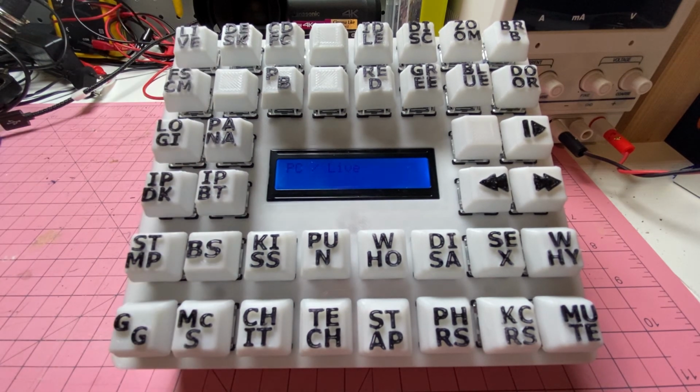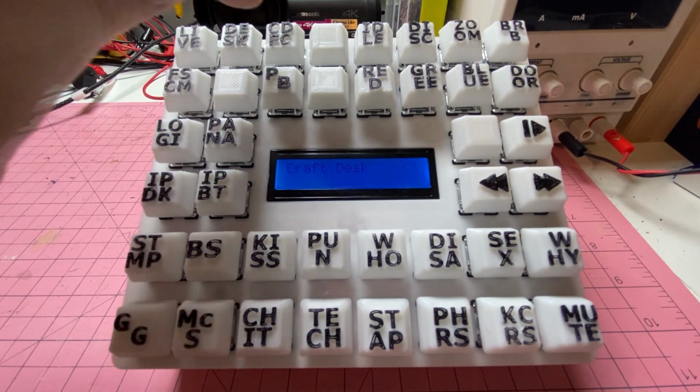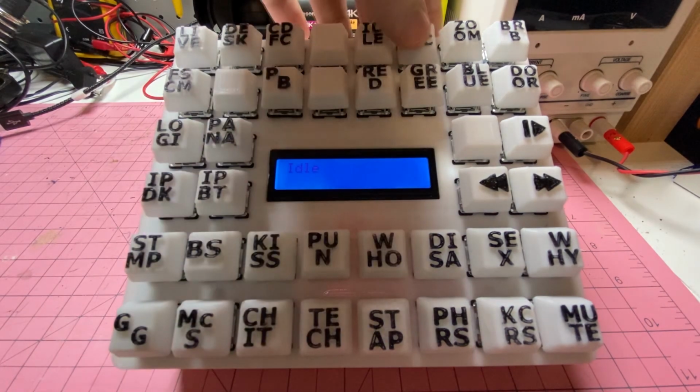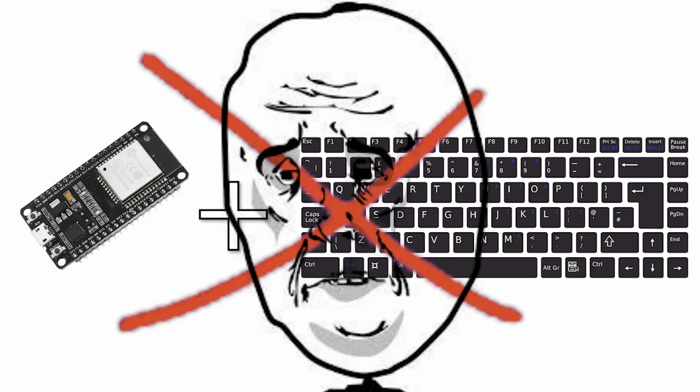You may have noticed some blank buttons and media keys, which I haven't assigned yet. Believe it or not, I actually ran out of things to assign, which is great. In terms of media keys, I'll need to wait for support to send keystrokes in Kruiz Control, as the ESP32 doesn't support the keyboard.h library. You could use a Pro Micro and connect it via I2C if this is something you want now, but I've not done it and frankly can't be stuffed.